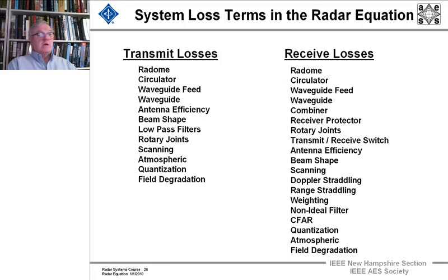It ain't going to work the way it does the first day you put it out in the field. Different components, they're not like your hand calculator that just works and just dies. There are enough analog systems in the transmitter and in the receiver itself that they will slow down in efficiency. Rust will occur. All kinds of different physical things, and these are what we call field degradation losses. They all have to be taken into account.